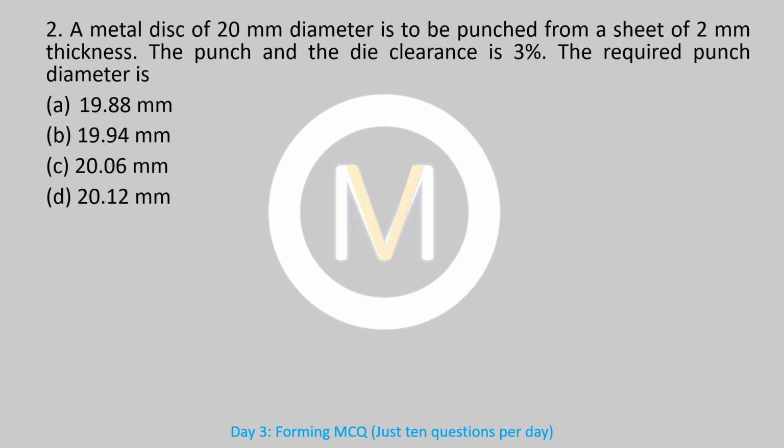So here the important part is the difference between punching and blanking operation. So what is the useful part and what is not useful. Take the reference of the punch that you do directly in paper. Here we are doing the punching operation. So our paper is important and the punching we are doing will be scrapped.